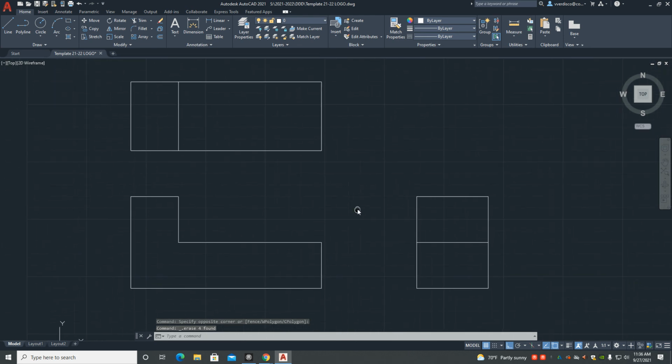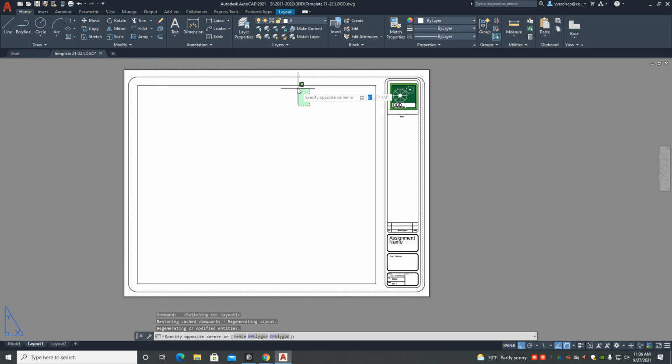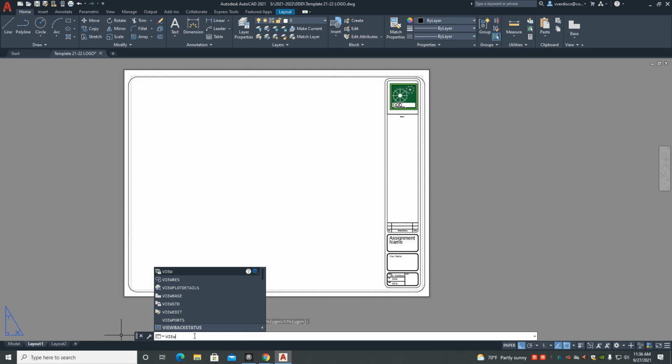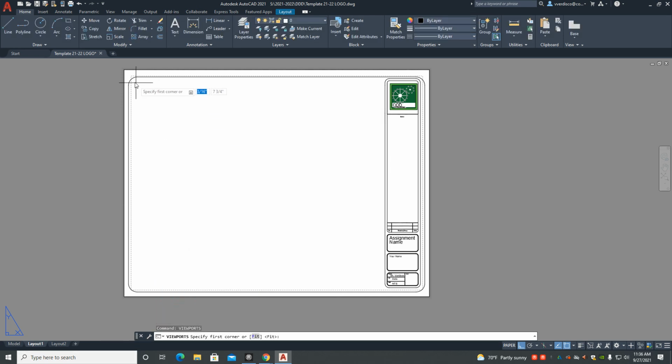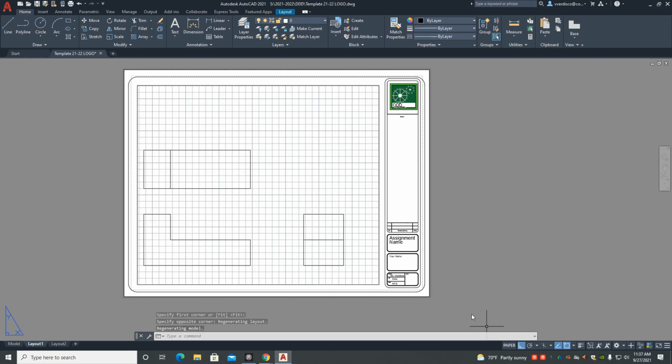There's our 3 views. Now, I know you know how to do this, but I'll just show you really quick. We're going to go to Layout, and I need to put a viewport in here if there's not one already. There might be one already, but I'm going to go ahead and put a fresh one in. There we go. Single. Okay. Float until you see the little plus sign. Stretch it out. Leave a margin. And all right. So now we need to work inside here.